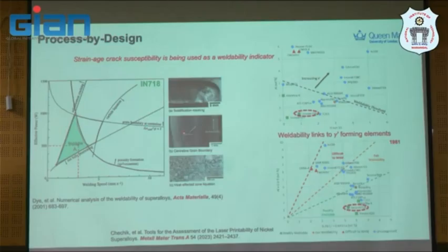If you're talking about carbide liquation here, I mean not fully penetration, porosity formation, grain boundary, and then solidification cracking. This is a working condition only for this Inconel 718, under the condition investigated here, definitely this is for welding. So they didn't do anything at that time. They identified this defect and plotted the diagram. And you will see that it's quite complex, even for something we call printable material.